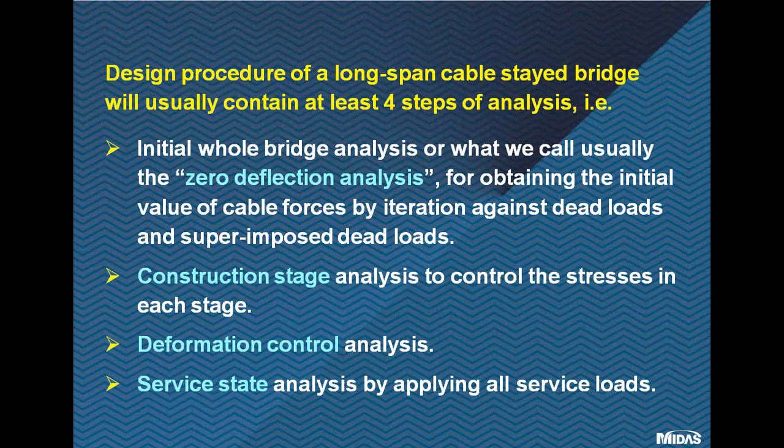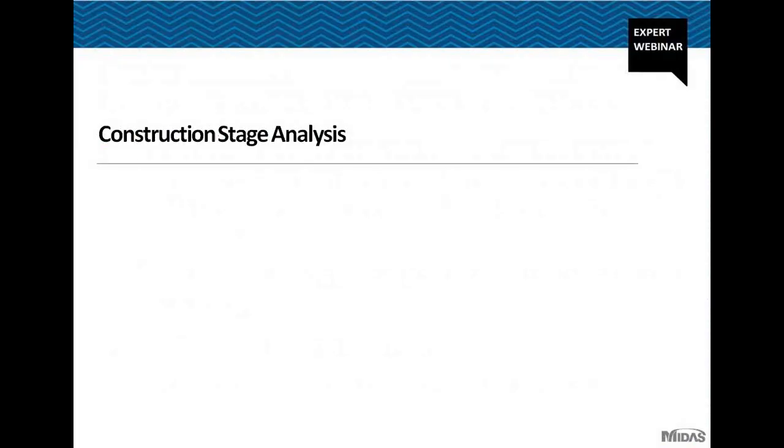The second step will analyze the construction stage in order to control the stresses, including the cable forces in each stage. The third step is to analyze the deformation for mainly the deflection control. In the fourth step, we analyze the service state by applying all service and transient loads. How is the construction stage analysis?